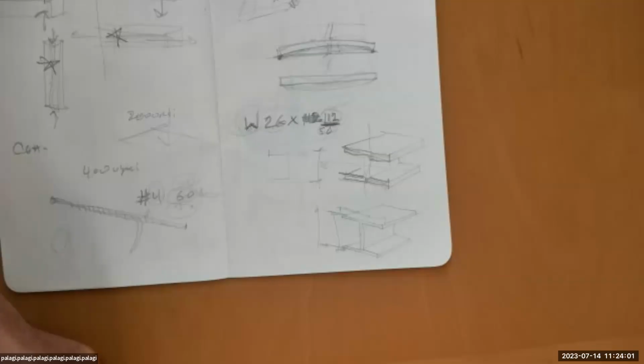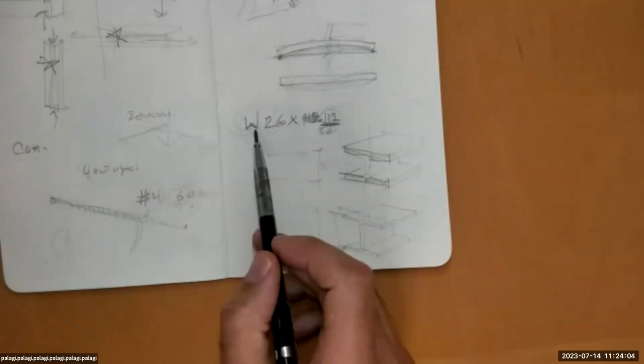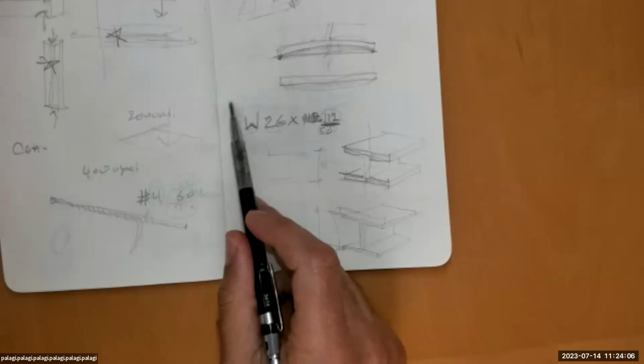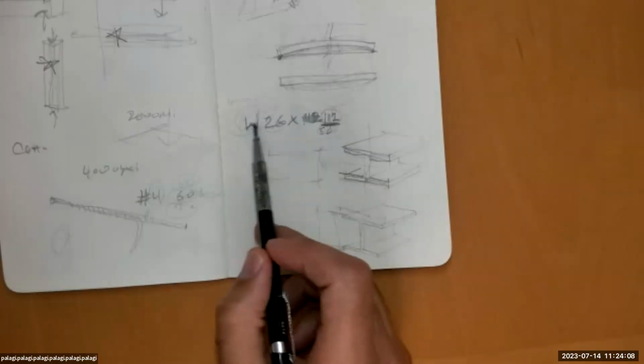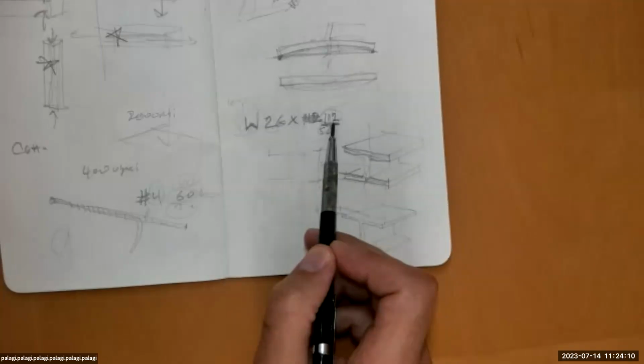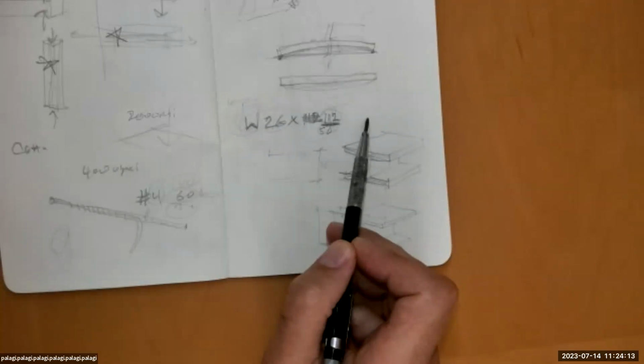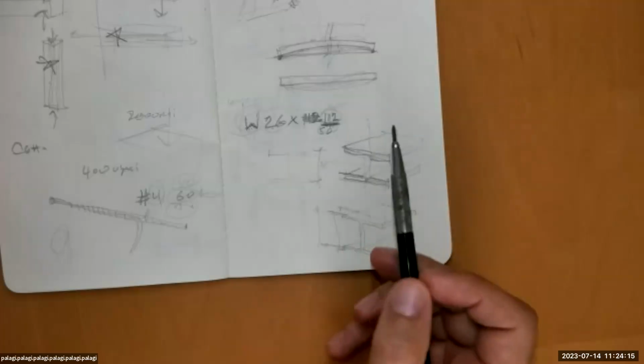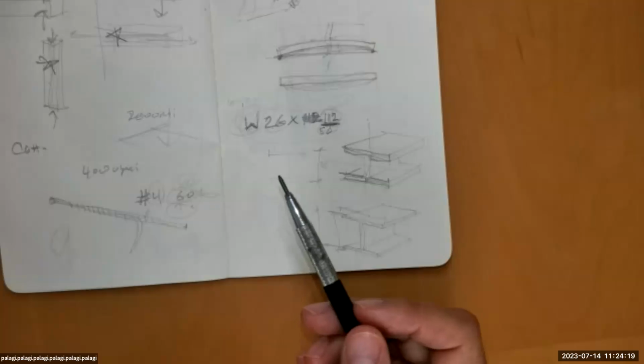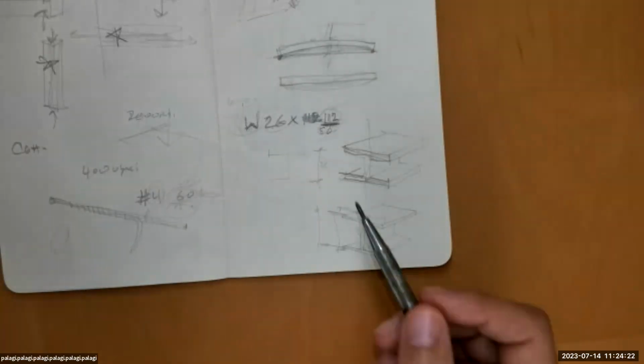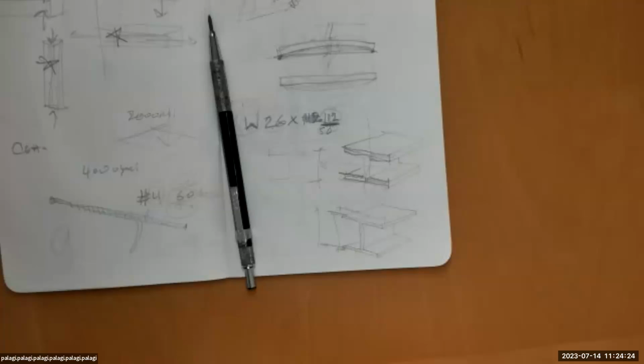So it's not about its shape. You're just buying this and they can add it up. If you had 1,000 linear feet of this cross section, that's 1,000 times this weight. That's how much steel you purchased. It's a price per pound of steel, so it's an easy way of calculating costs, because it's just pounds per linear foot. Now, if we have that pounds per linear foot, we can figure out how much weight this roof framing is.